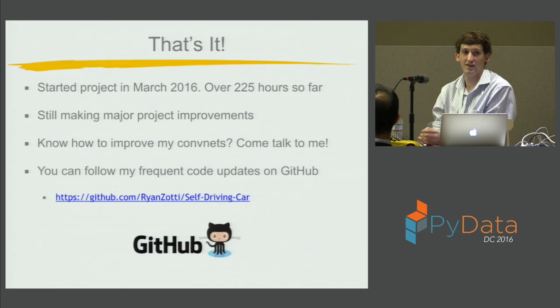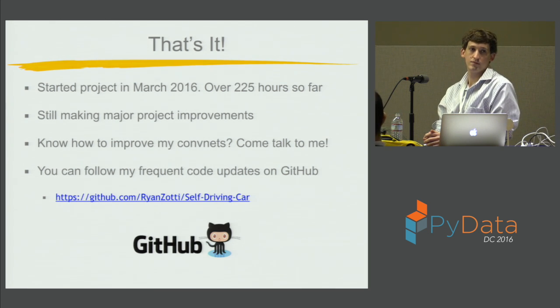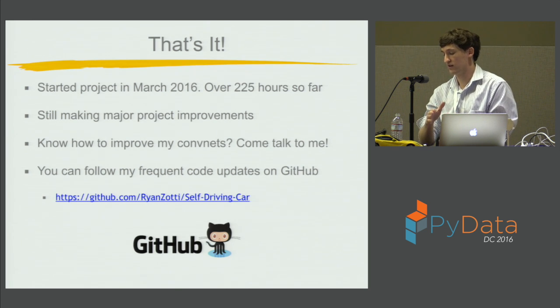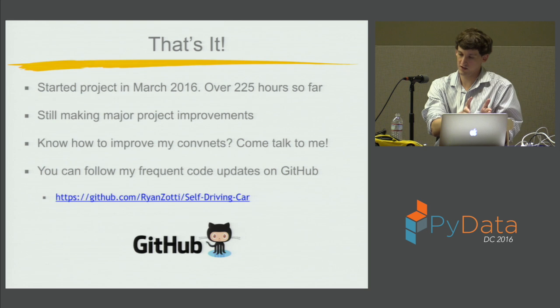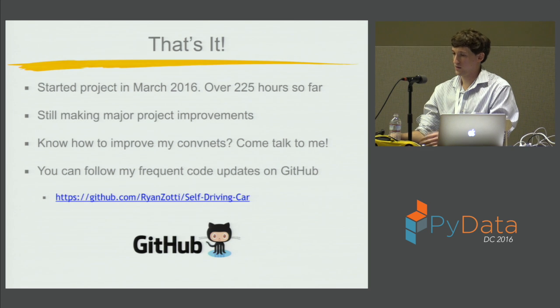Cool. Yeah, question over there. So how do you make the training data set then? So you're driving it off the track and it's driving on the track? Yeah, good question. So that's actually a really complicated part that I kind of glossed over. But the answer to the last part of your question first. You never really want to intentionally drive it off the track because then it'll learn to do that. But what does really help is to start it almost coming off the track so that it learns to correct itself. And I had to do a lot of training examples on that because with the latency and everything like that, it has to be able to correct itself quite a bit when I would deploy it.